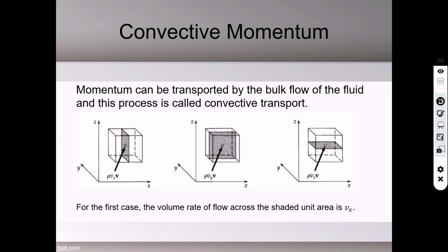So it has a mass flow, but how to calculate the force? We use Newton's second law. Newton's second law is d(mv)/dt, not F equals ma, okay? Not in that way. And that should equal m dv/dt plus v dm/dt. If the flow is a stationary flow, not static, I'm sorry about it, then you don't have the dv/dt term.